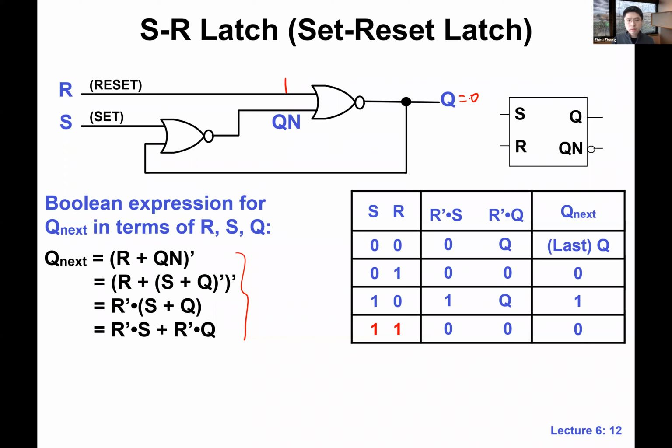Of course, you might be thinking about timing as well. That's something that we're going to be talking about. This means we usually hold R and S stable enough that it's not going to glitch or oscillate. So let's just think that we hold R and S stable for a period of time. So when R is 1, Q is going to be 0 for sure.